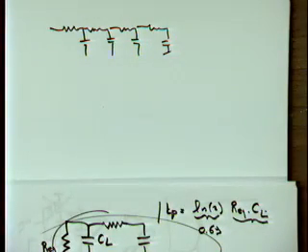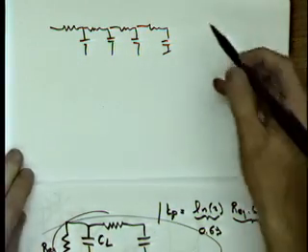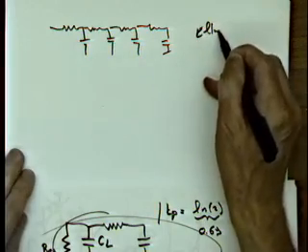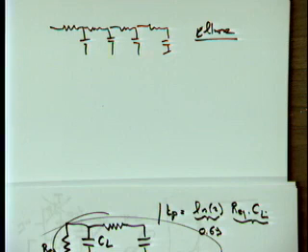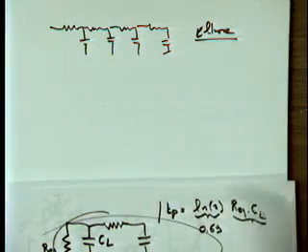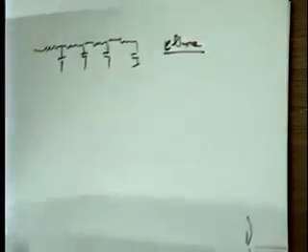But later on we're going to show a technique called the Elmore delay expression. Just remember the name for the time being. We'll come back to that later. It allows us to take a fairly complex RC network and say, hey, that's the delay of that network, without having to understand all the intricate details of how the waveform changes. Okay? You heard what I said, so it should be pretty clear. Okay, so that's the transient.